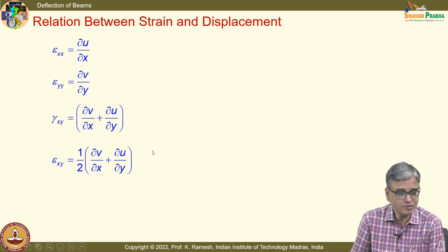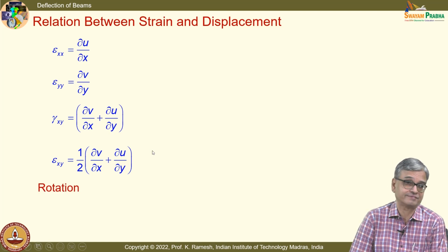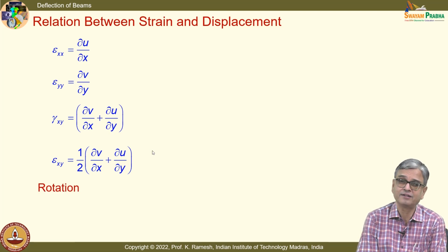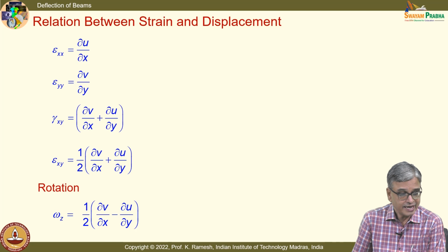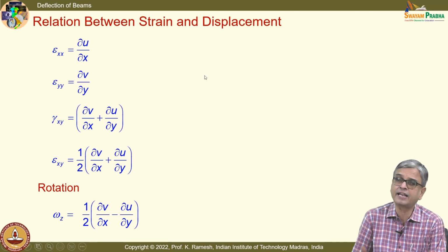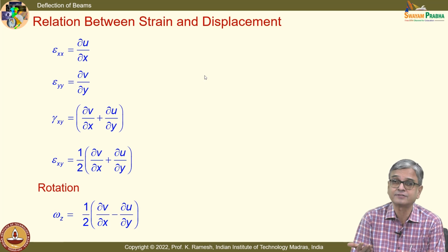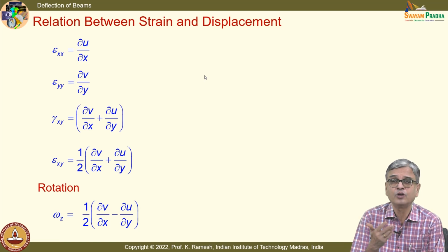And we have also discussed rotation. You remember? We have also developed rotation. So when anything gets deformed, it can have all of the strain components as well as rotation, because it all comes from the way the components of displacement u and v vary over the cross section.